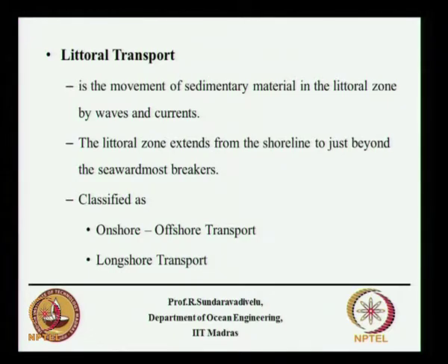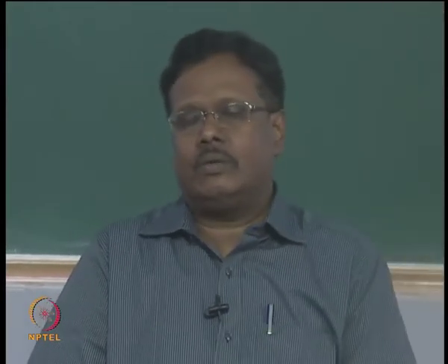There are three directions. One direction is along the shore, another is perpendicular to the shore, the third one is the water depth. So these are the three directions. So you can have an onshore to offshore transport, just as I have shown in this sketch, or we can have a longshore transport.